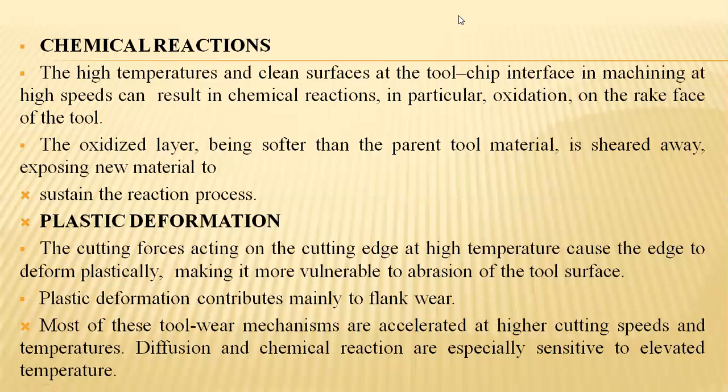Coming to the plastic deformation, the cutting forces acting on the cutting edge lead to high temperature stress involvement, which deforms the edges plastically in the plasticity range. Mainly this contributes to flank wear.